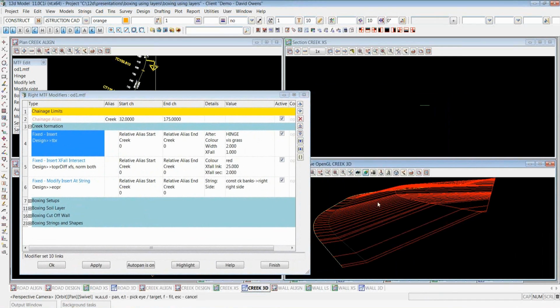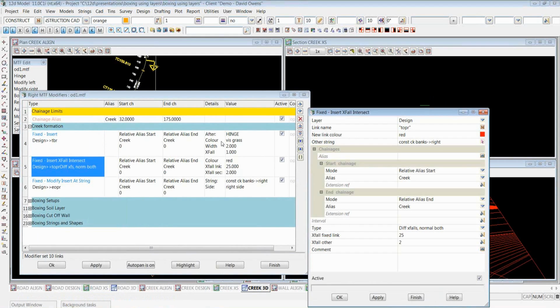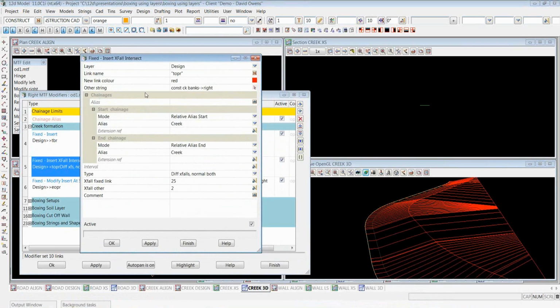Yeah. In this case, what we're actually trying to achieve was the maximum amount of usable open space, I guess, park, picnic corner area. So by having a string draped along the limits of the area that we had to work with, running an insert crossfall command to create a link at the intersection of slopes of a 1 in 4 from the edge of the drain to a 2% slope passing through that string, a construction string.